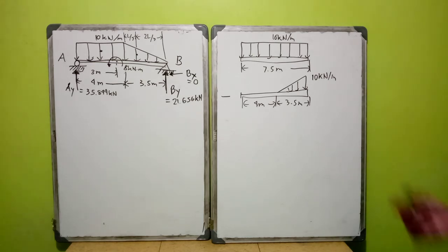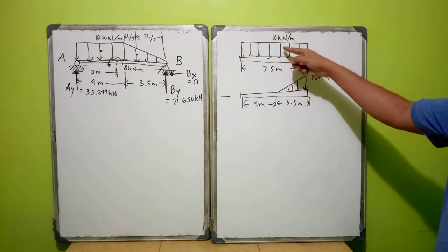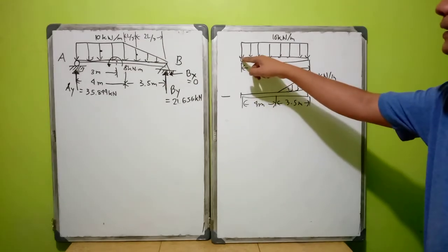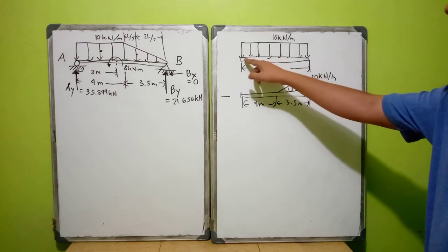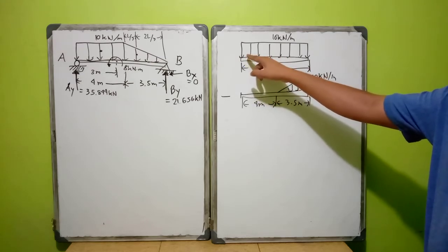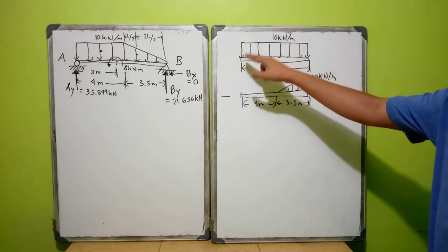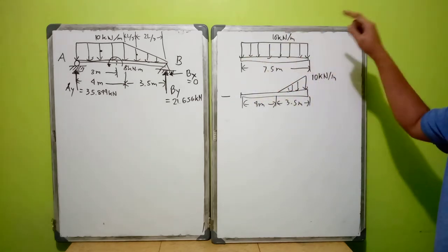So why do we do this? In order for your shear and moment equations, as we discussed in part 1, to be applicable, that distributed loading, as soon as it starts at any point from the left support, if it is a uniformly distributed rectangular load, for example, it should continue from that point until the end, until the right support.